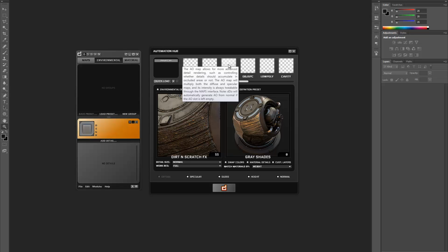And for even more advanced control, use object space maps. The object space normal map lets you filter the direction of the details you create, and this will let you simulate really cool effects such as dust only being gathered at the top of something, or mud spatter coming in from below on a car or a truck. You can create some really cool dynamic effects on your models.